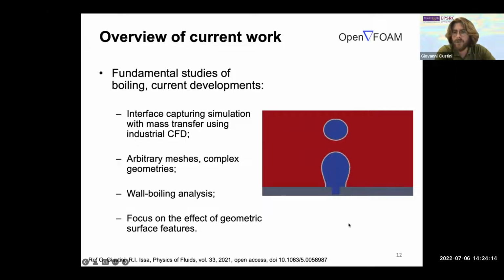And on the right here is an example of the things that one can do with this kind of methodology. These are actually images of bubble growth in pool boiling using the fluid properties of sodium, pool boiling from a cavity on a surface. So in the video, this isn't a case of gas injection from an orifice, but a bubble growing at a surface with particular features, in this case, a circular indentation, a cylindrical cavity.